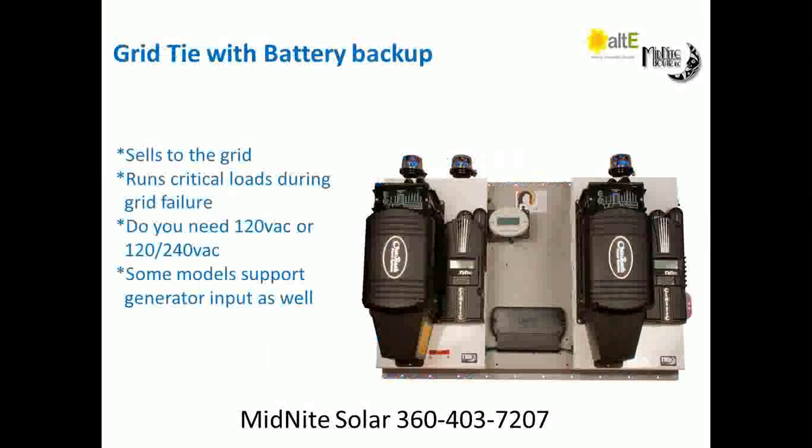Now, if you're doing a grid tie with battery backup, that changes. You need to know, first of all, what time frame you want to run the loads, if it's 12 hours, 24 hours, and that will help you decide how much battery you need. The other factor that changes is, instead of that 50% state of charge, the rule of thumb on battery-based grid tie is we're allowed to go to 80% depth of discharge. Just because we do it so infrequently, we're not afraid of abusing the batteries at that one point. The batteries are going to die of age before they die of use, if that makes sense.